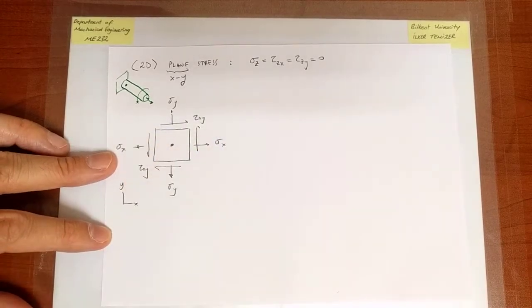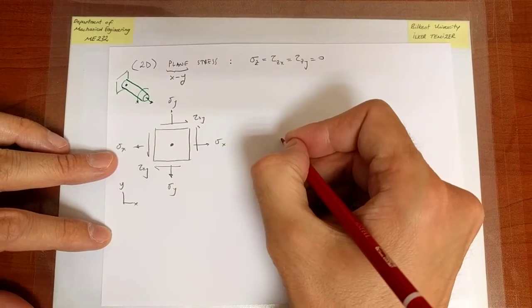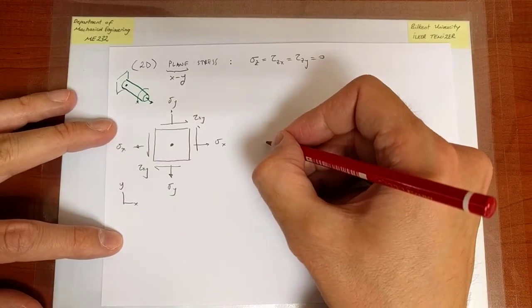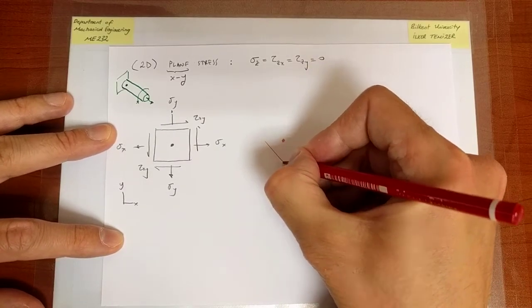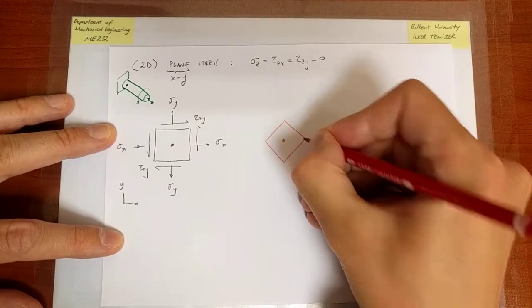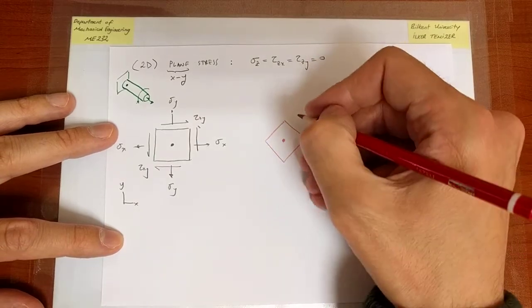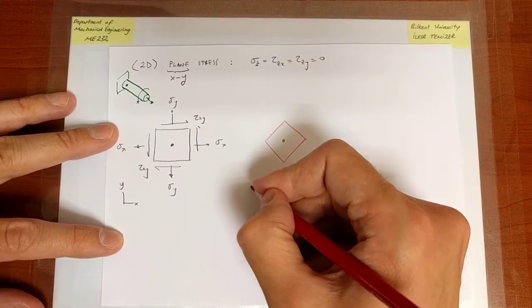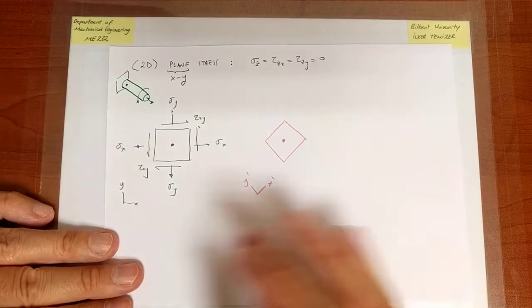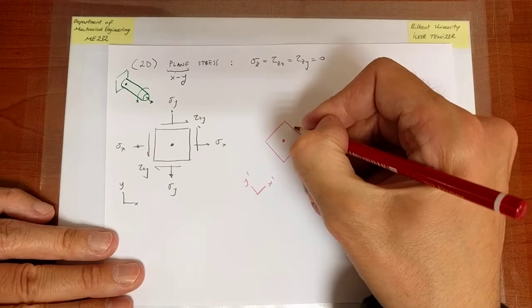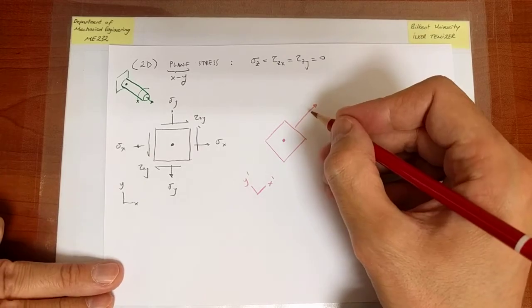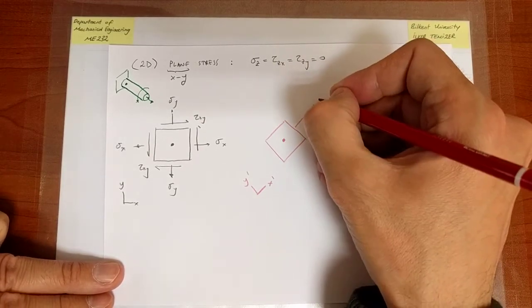Now at the same point, what I want to do now is answer the question, well, if at the same point I take different cuts, so in other words, if at the same point I choose that geometric representation of the element, small chunk of material, oriented in a different fashion, and that choice is associated with new directions, let's say an x prime direction and a y prime direction, then we've just discussed that the stresses I measure, the state of stress is the same, but at that point, the way we quantify the normal stresses and the shear stresses, their values will change.